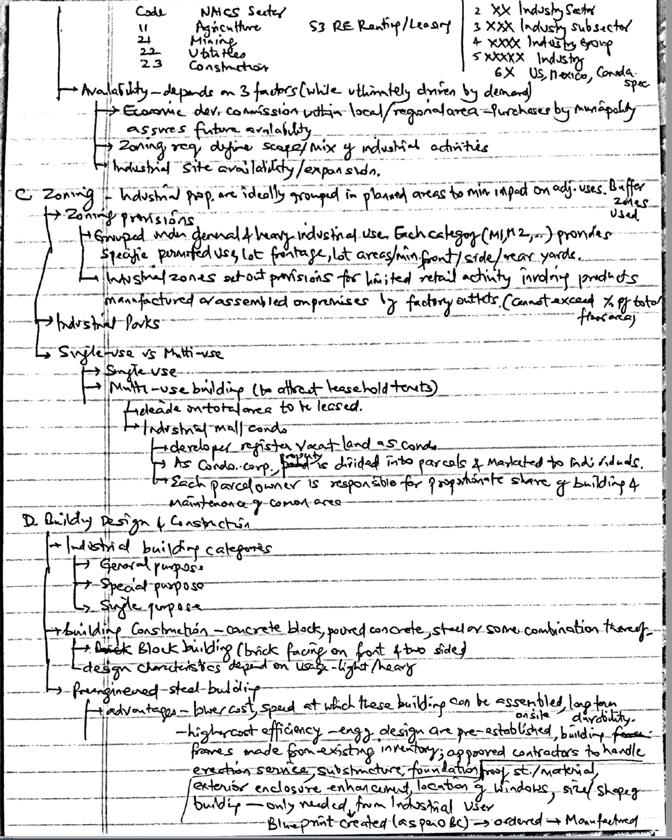A sprinklered building is equipped with a system of automatic sprinklers. The sprinkler system runs by pipes, risers, mains, and sprinkler heads. Five types of sprinkler systems are commonly used in the marketplace: wet pipe, dry pipe, pre-action, deluge, and combined dry pipe and pre-action.